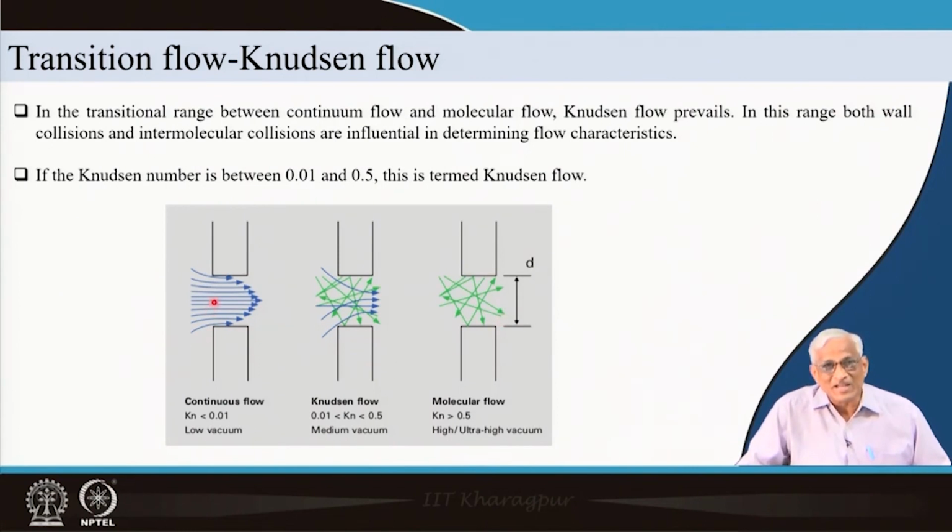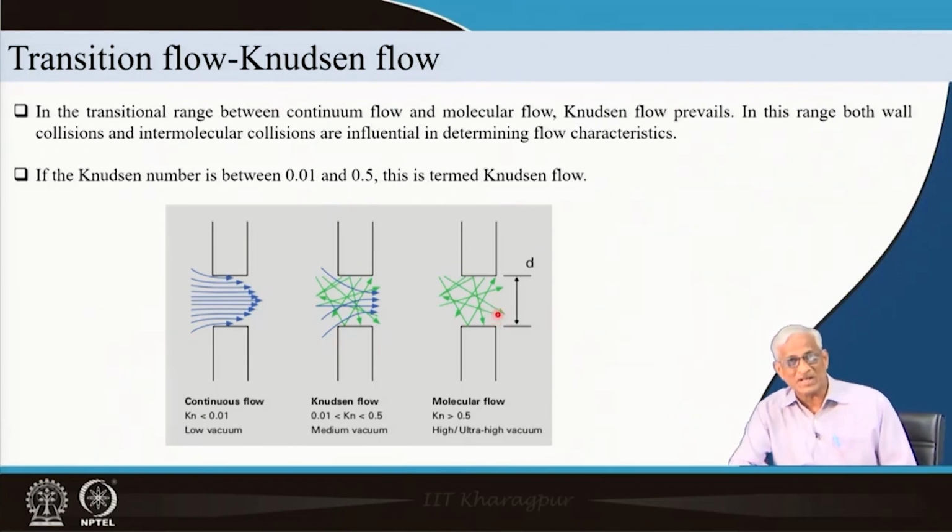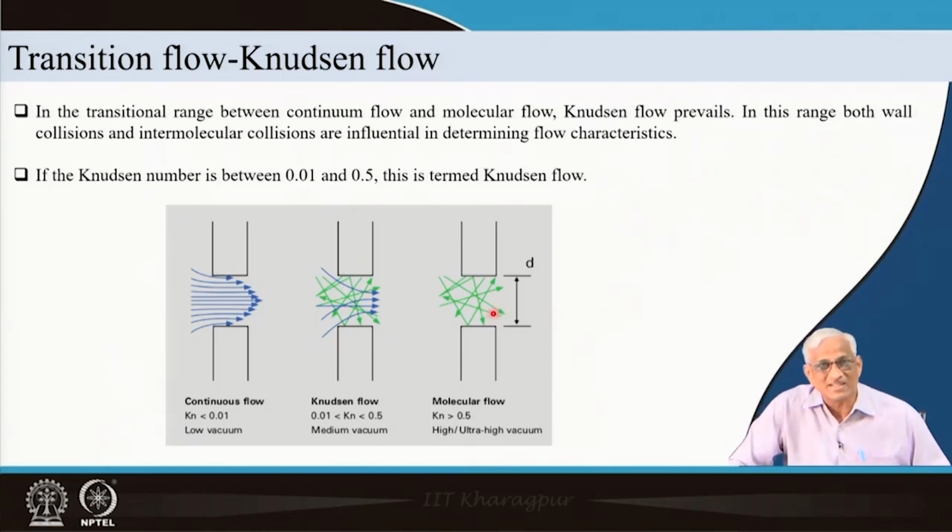Briefly speaking, here there is continuity and here there is a sort of discontinuity, because each molecule is independent. Some molecules can come back also, depending on the local roughness there. There is nothing like flowing across a pressure drop. Pressure drop is not the main reason for flow. It is only the molecular concentration differences and statistical chances for left to right and right to left movement of molecules, that is called molecular flow. It is purely statistical, whereas here pressure drop is responsible, and in between there is a sort of flow where we get the concept of pressure drop being responsible for the flow.